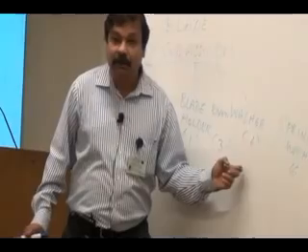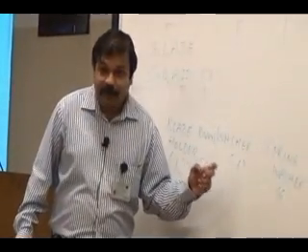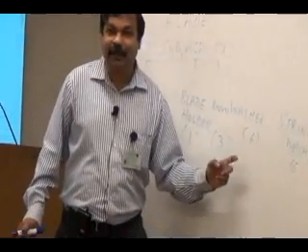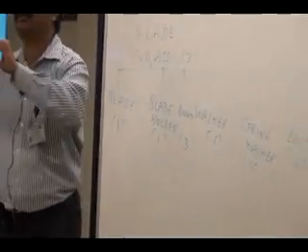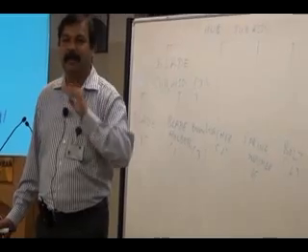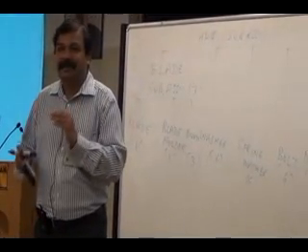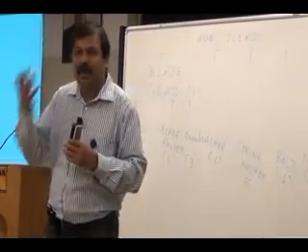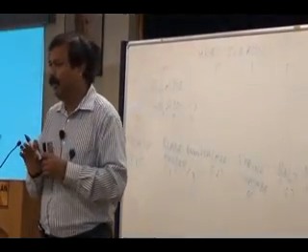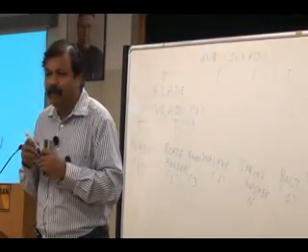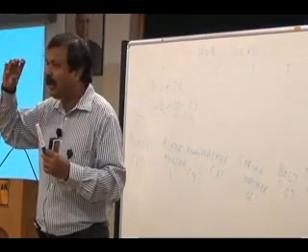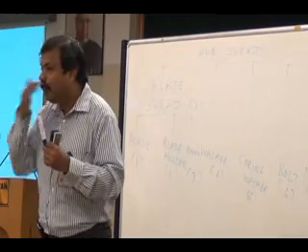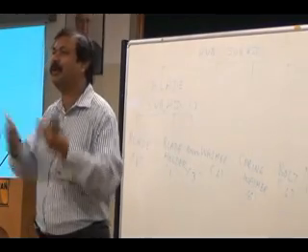Do I require a washer? No. Yes, you will appreciate it later. I do require a washer because the clamping pressure must be evenly distributed onto the surface of the blade. See, the idea of a washer is again a beautiful mechanical concept. When you tighten the bolt, there is something called the clamping force. That force must be distributed over an area.